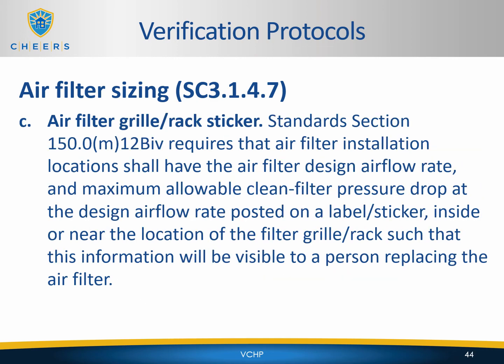Air filter grill or rack sticker. Standard section 150.0(m)12B4 requires that air filter installation locations shall have the air filter design airflow rate and maximum allowable clean filter pressure drop at the design airflow rate posted on a label or sticker inside or near the location of the filter grill or rack, such that this information will be visible to a person replacing the air filter. So this is just the standard labeling requirement that is applicable to all ducted systems under the standards.